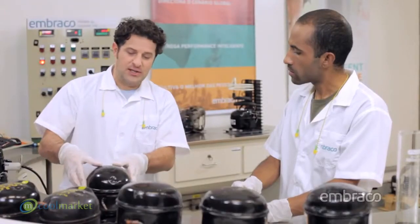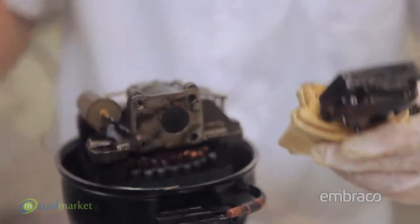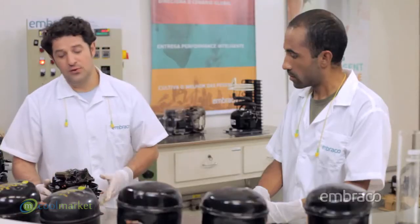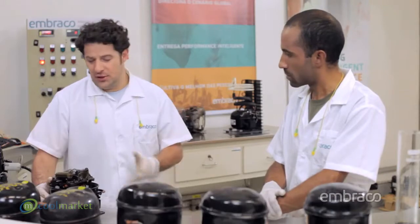Got it. And what can this residual moisture cause in the system, Peter? The carbonization of the valve plate and the compressor head, Mark. Can the refrigerant fluid have something to do with a moisture problem? Well, if the refrigerant fluid doesn't have adequate quality, it may contain residues or impurities from the manufacturing process, such as non-condensable gases and moisture, which can indeed be sufficient to contaminate the system.